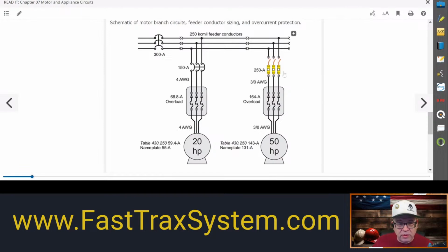We did exactly what it says. This was the larger of the two short circuit ground fault protection devices. We took the larger, as it said, and we had already done this one. That's why we do all these strings. We've already done this one at the 175%, the same way that it says in 430.62. And it says you take the sum of the other motor that's in the group. So this one's at 250 right here. We took that and added the 59.4 amps to it. That gave us 309.4 amps. But what did it say back in 430.62? Okay, what did it say?